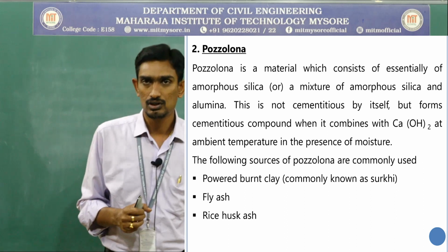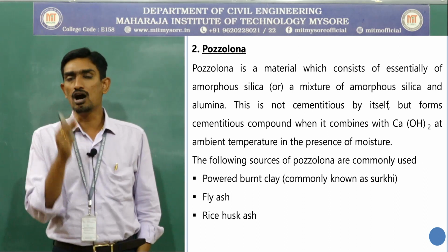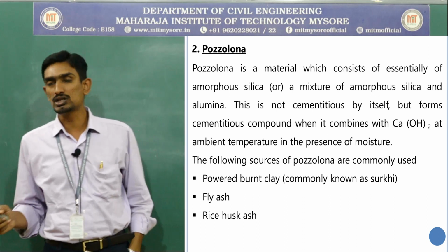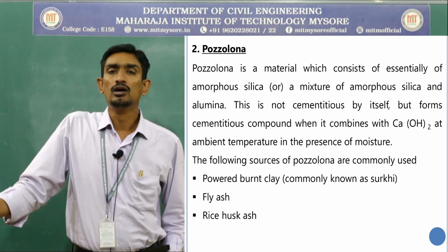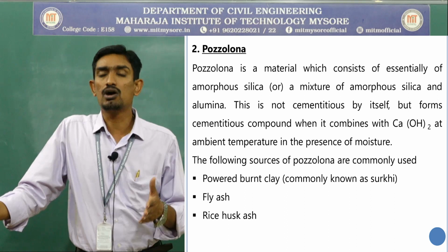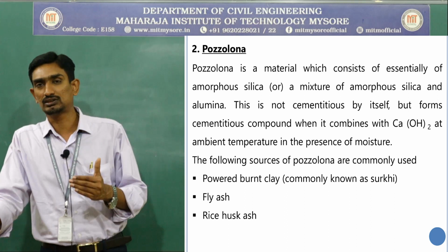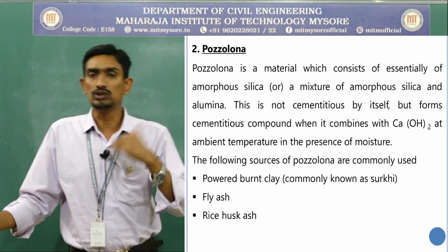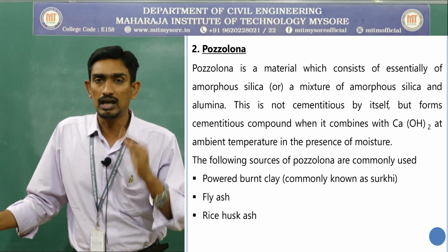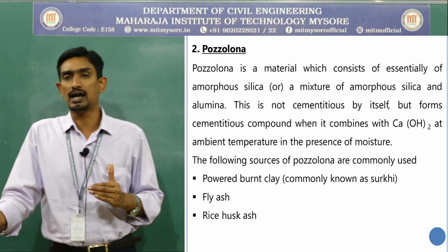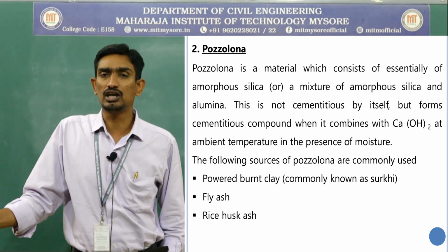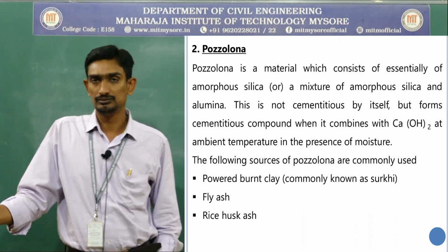This is called fly ash. So fly ash is a predominantly used pozzolanic material that can be used as the best replacing material for cement also. So I mix this fly ash, which is a pozzolanic material, with the cement. Then it is called Portland pozzolana cement. There I can reduce the carbon dioxide emission. It is completely eco-friendly, I can say a green product or green cement.